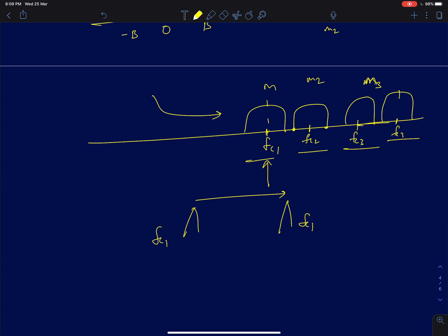If you recall your correlation receivers, I'm just going to multiply it with the carrier frequency and down-convert the data. Okay, demodulate the data. So this phenomenon is what we call frequency division multiplexing. Each user gets a different frequency channel. This is what we will be talking about in a little bit more detail.